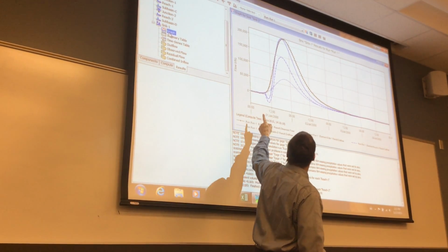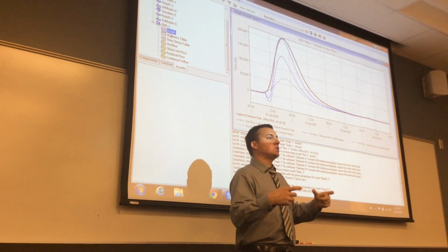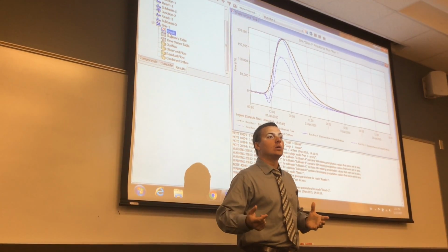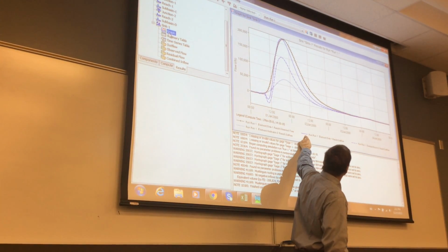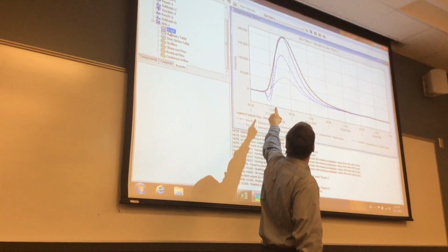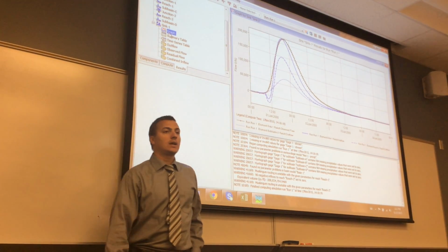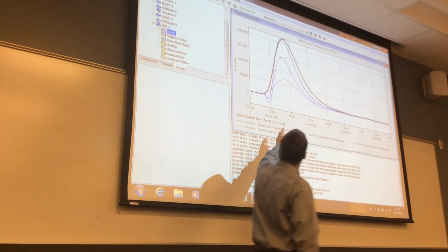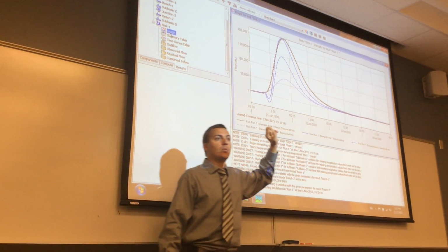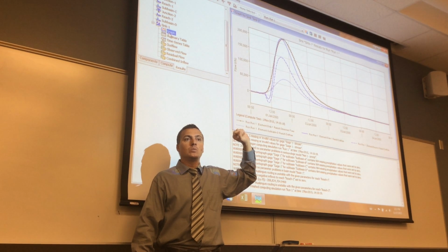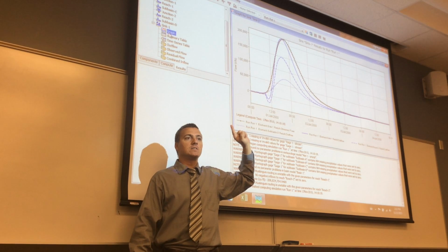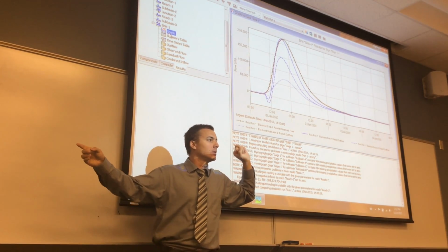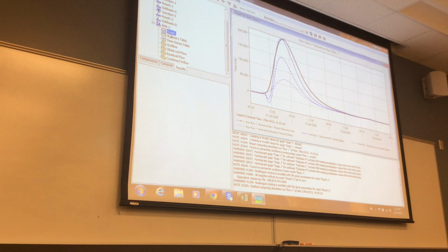Black means measured data. That's what we measured. That's the time series we copied from Excel. That was our initial hydrograph. Blue means our final result at the sink. And the other two are the combinations of what? The reaches. One reach and subbasin D. Because that's what's coming into the sink. Subbasin D plus what's being routed through the reach.